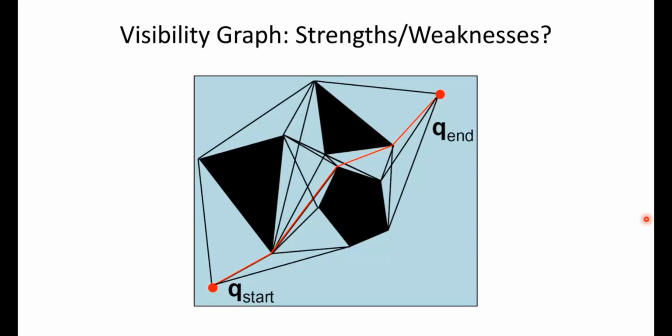It might make silly paths if I have weird geometry or small objects. Well, this will give me the best path subject to those obstacles, but it's going to look a little strange because we'll be hugging a lot of walls. You can just inflate the geometry of the obstacles, though, to give you some padding room. Absolutely. Yep. So again, I can approximate these geometries however I want, right? But that's the trade-off of optimality versus practicality.